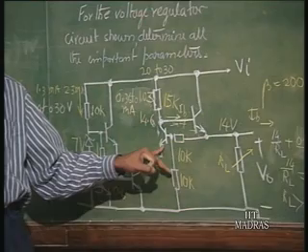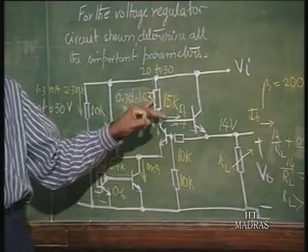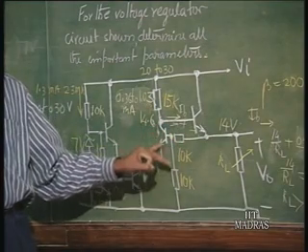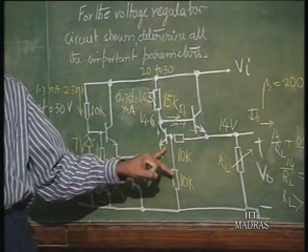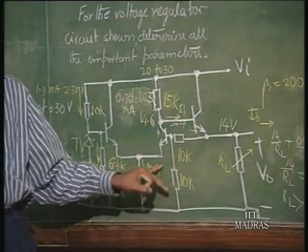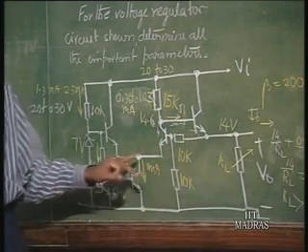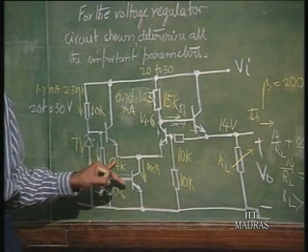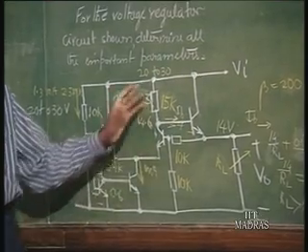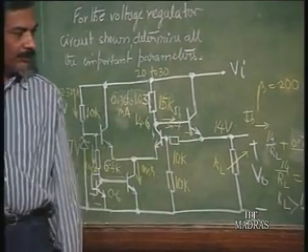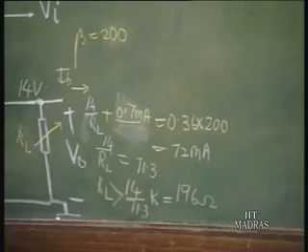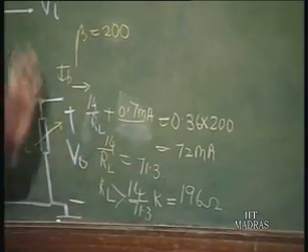The rest of it can go into this, that is 1.03 minus 0.36, about 0.64, can go into this very happily, because it still has some current to be given to this, that is 0.36. So, this circuit will function up to this kind of load. Lower than this, it will stop functioning.